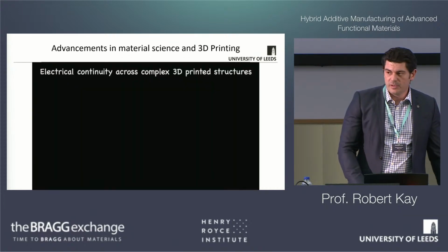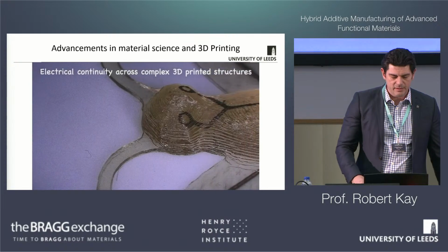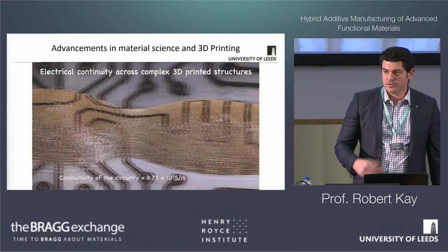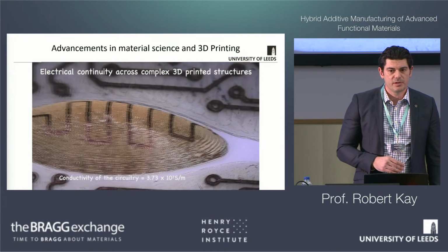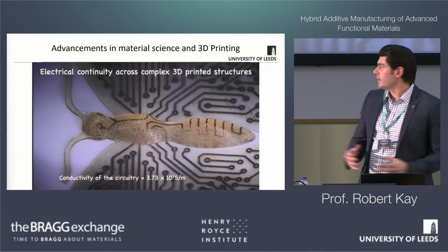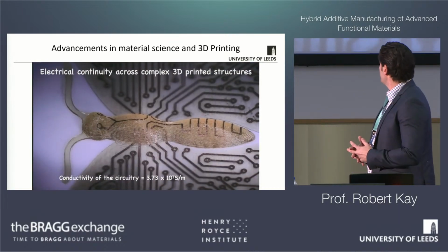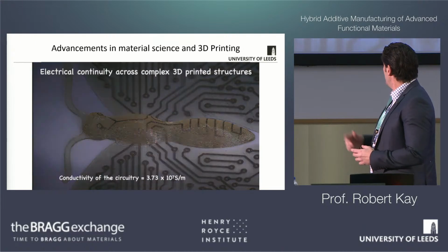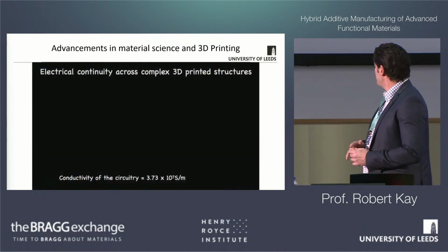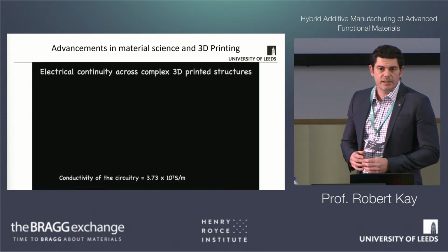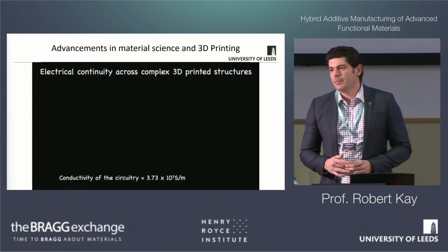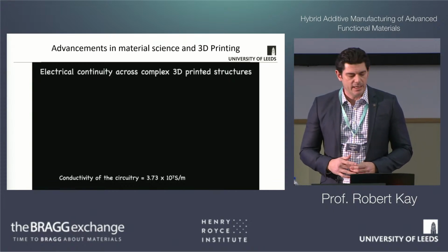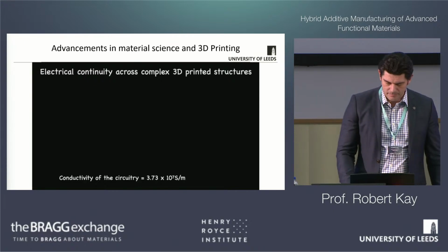The next question was, well, this isn't printing paste, so is this going to actually bridge across the individual printed layers, or are we going to have open circuits? And we're really pleased to measure the continuity across that. And when we did the 4-point probe measurements, we found that it had very good conductivity, about 2/3 the value of bulk copper that you'd find in a handbook. So that's very similar to electrolytic copper deposited today.